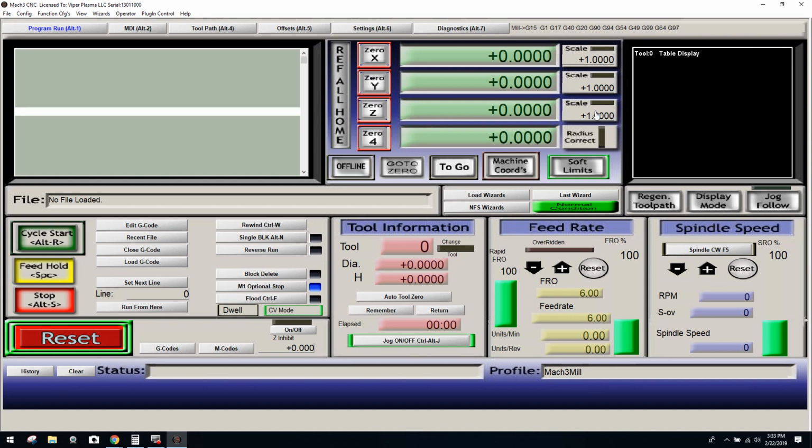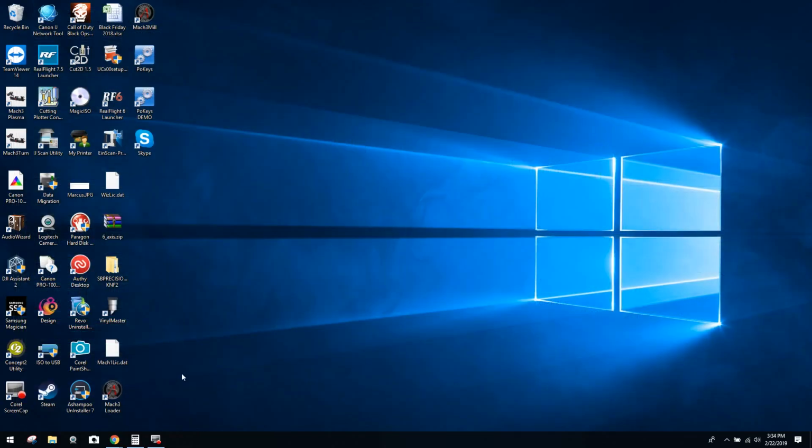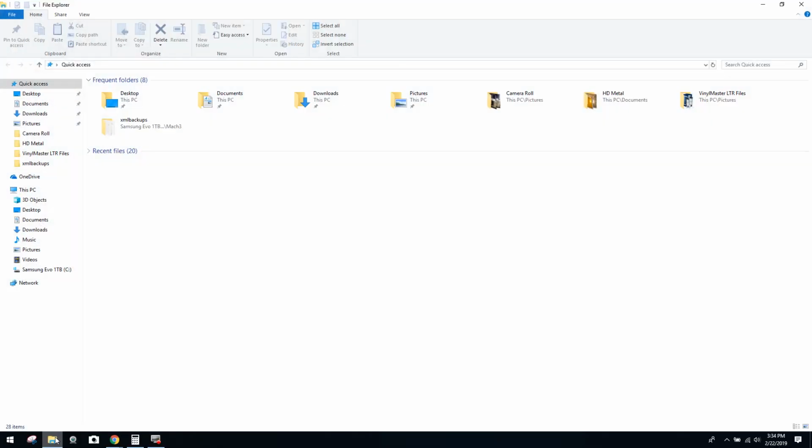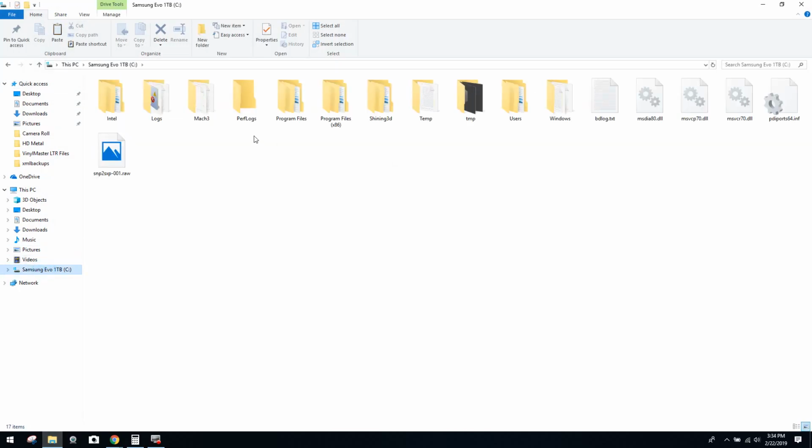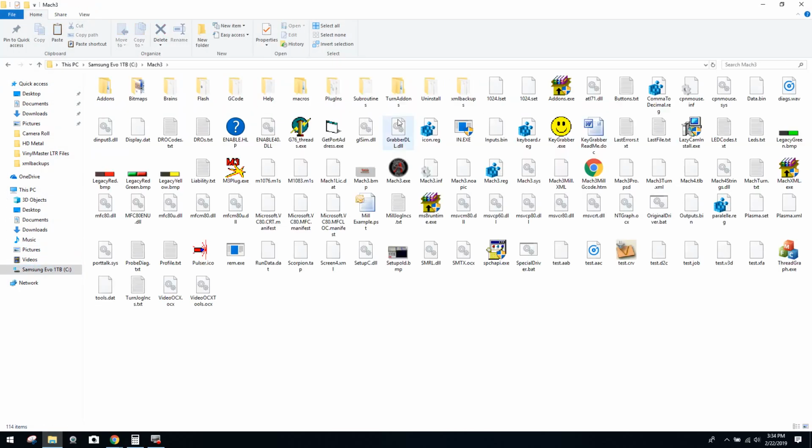And I don't care who you are or how well versed you are in Mach, it's always smarter to have actually two backups. You can naturally use the software backup that I just showed you, but also making a hard copy backup is excellent as well. That being said, we can end out of here again. And as we did that, we'll come back over here, and one of the things I want to point out is that if you did want to do a hard copy backup, naturally get yourself a flash drive, very simple to do.